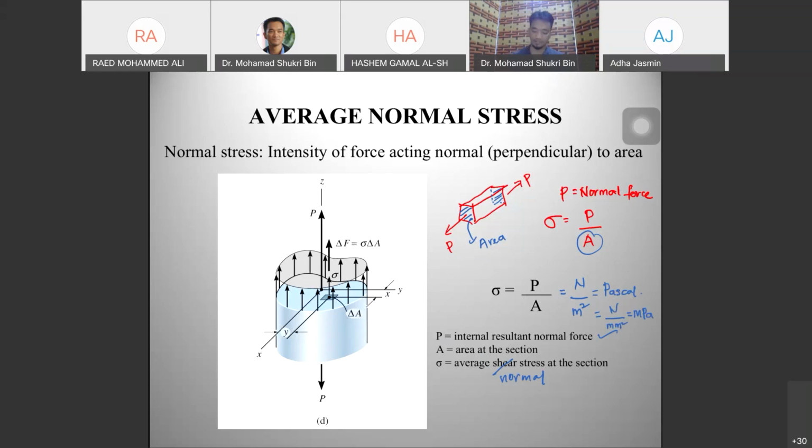But this is the simplification or the trick, because if it gives you, let's say 20 mm, you need to convert to meter. It is very challenging, right? You have 0.02 meter, and you want to multiply by 0.02 meter. So this is challenging in your calculation. So for simplification, you can use mm directly, but your unit later on is megapascal.